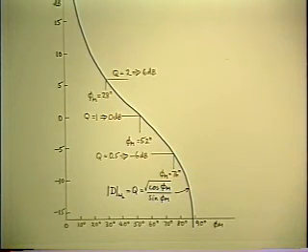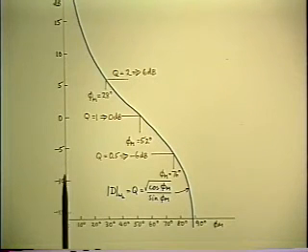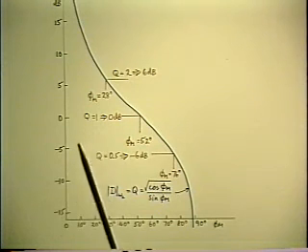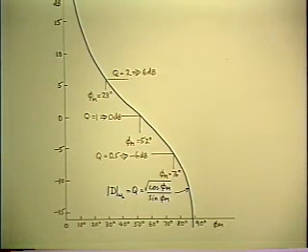There's a one-to-one relationship between the frequency domain, which is what this Q factor refers to, that is peaking at the end of the closed loop bandwidth according to the value of this Q, and the time domain response.